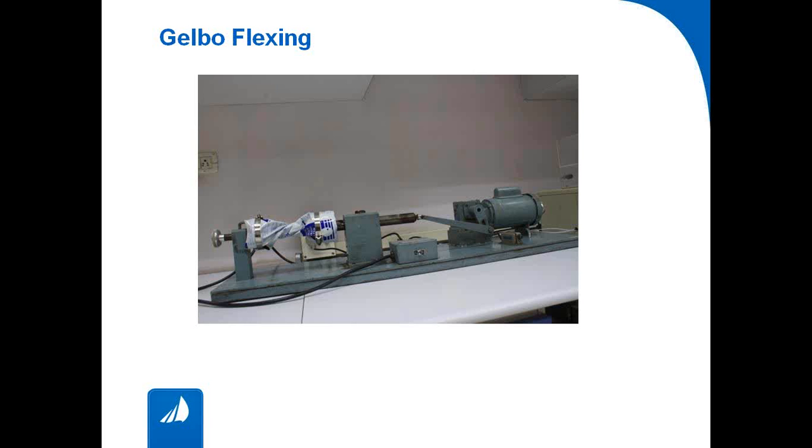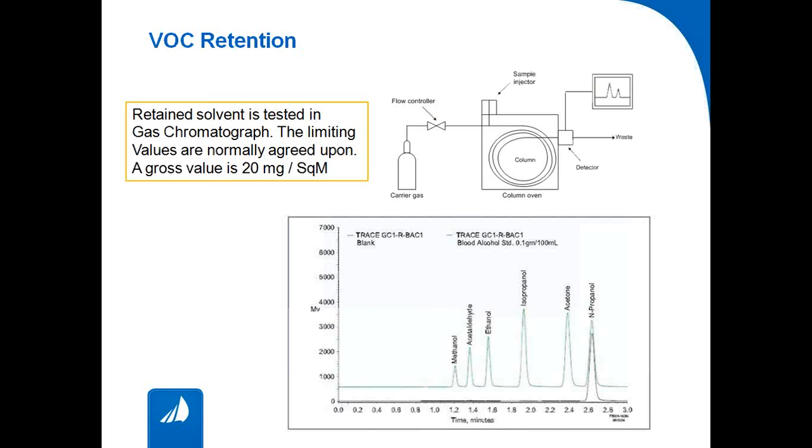So each cycle has a particular movement and degree of rotation. So we keep on giving different cycles and test it. There are American Standards also available. So we can give 20 cycles, 50 cycles, 1000 cycles, or even 5 cycles depending on the assessed application abuses of this packaging material. And as I said, we test before flexing and after flexing.